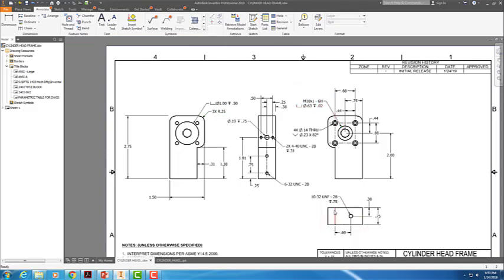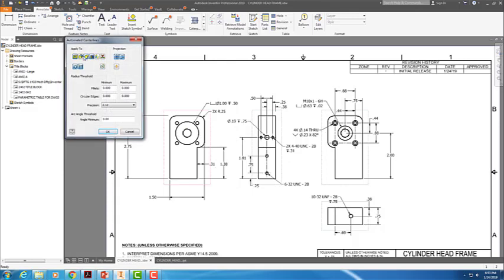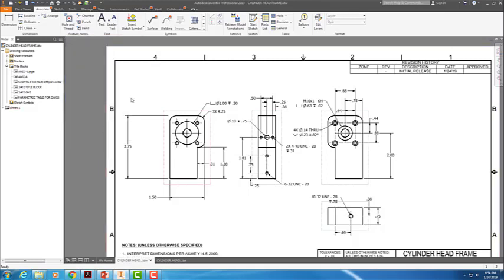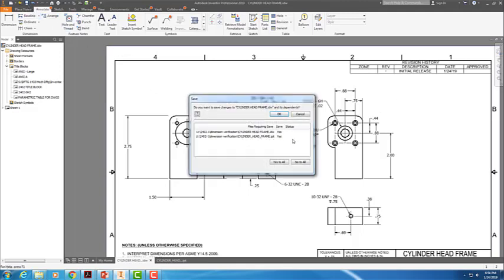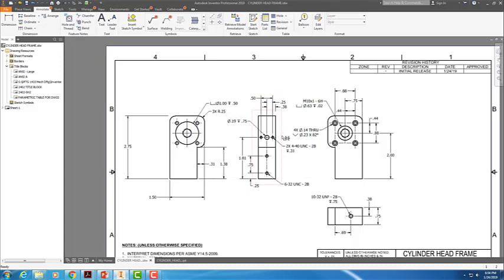Alright, now I'm at the end of my rope. I'm going to grab, holding down control, all four of these views, right click, automated center lines. These are already set up to be centered patterns, rectangular patterns, axial center lines, bullseyes, cylinders, revolves, and holes. And we set that up in the template itself, in this format. So now everything has the center marks. And I'm going to save this, not saving the part. And I'm finished with my drawing, but look at this one.